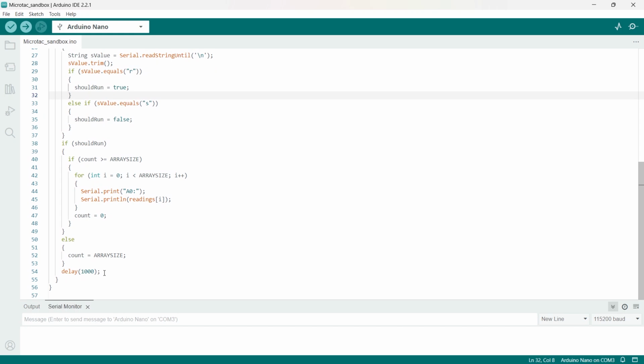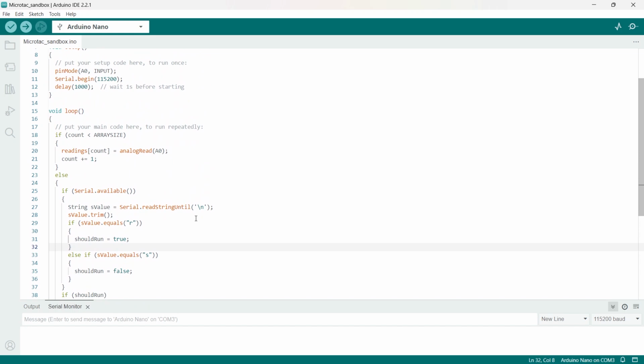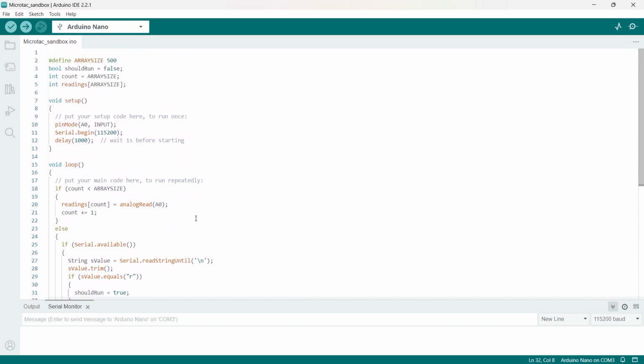I did put a 1-second delay in there just so there's a little pause before it repeats the cycle. I figured that's probably my best shot to really see the fastest rate that the Arduino can do this analog to digital conversion. According to the online documentation, the maximum rate is approximately 10 kilohertz. Of course, that assumes there's not much else the Atmega is doing during that time. Anything else you add, such as spitting out the data in real time on the serial port, is just going to bog it down, and I'm not going to get that sample rate.